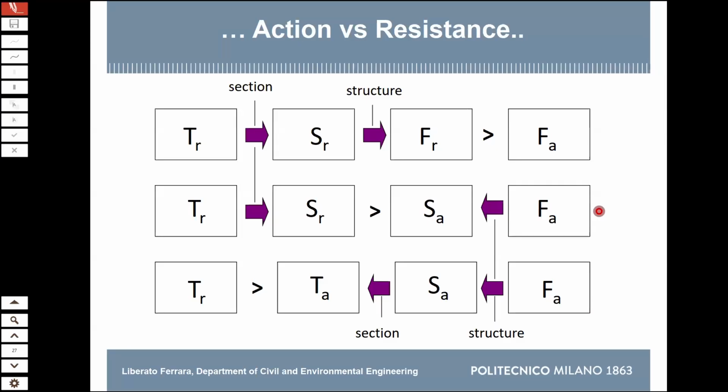Then there is the third level, which is what we use, for example, when we make the plastic design with a plastic hinge model. We have the strength of the material. We hypothesize a cross-section model and we calculate the moment capacity of the cross-section.